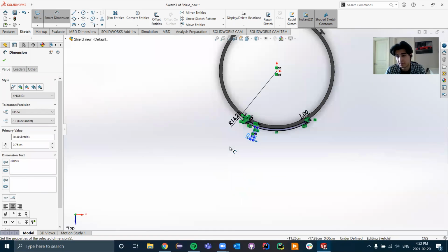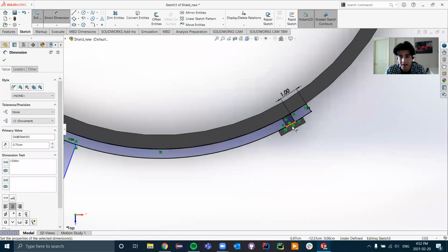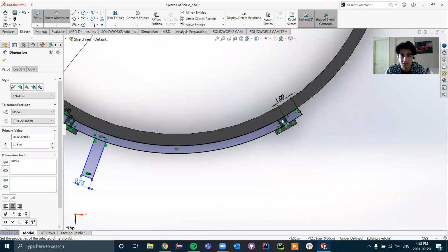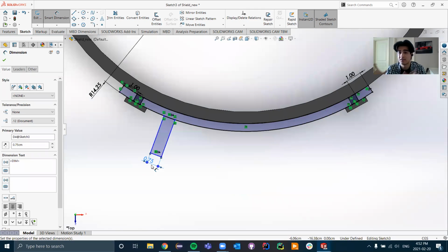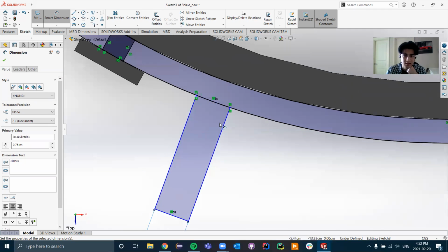It's not bad. Okay. And now you'll see the value of actually constraining your sketch, because if these parts of the sketch were underdefined and we did this, you can sort of imagine the entire circle moving along. So it's good that we actually establish these different dimensions right here, such that the sketch underneath doesn't move. So this seems to be fine. You can make it thicker, thinner, however much you want it. This is more of an approximation.